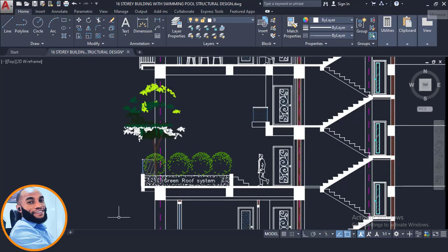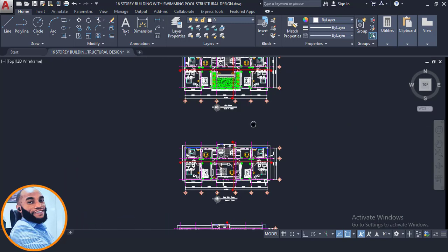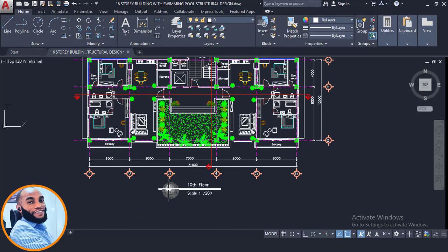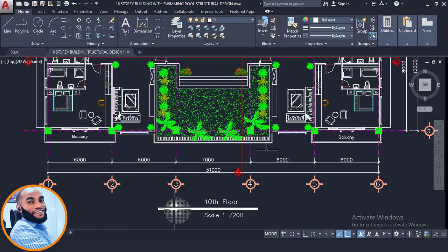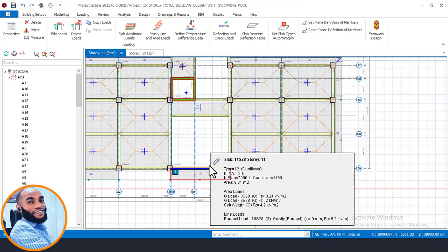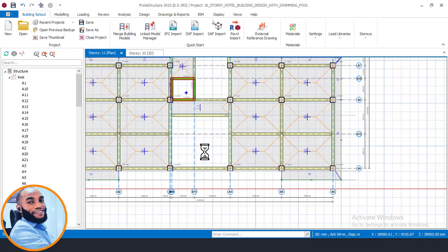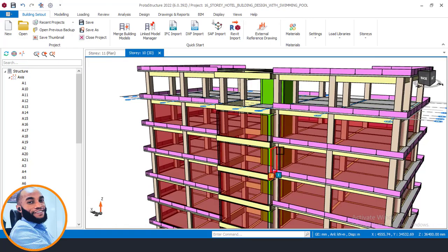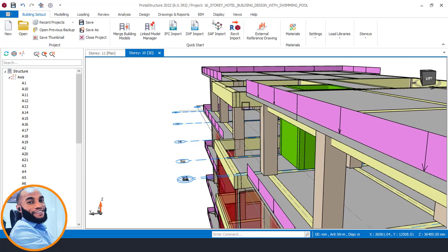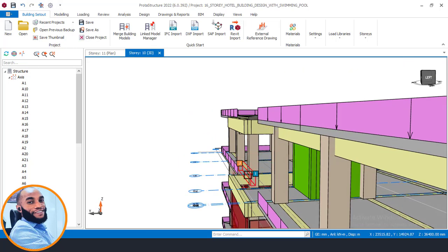So I'll also take off that slab because there's no balcony on this place here. If you also take the CAD file here, you will see that there is no balcony coming out. You can see that it is just flushing straight down, while this one was coming out, protruding out here. So I'll come here and remove this balcony slab on the 11th floor. So if you now go and check our 3D view here, you will see what we have just done so far, which is here. As you can see, this is what we have on that place.